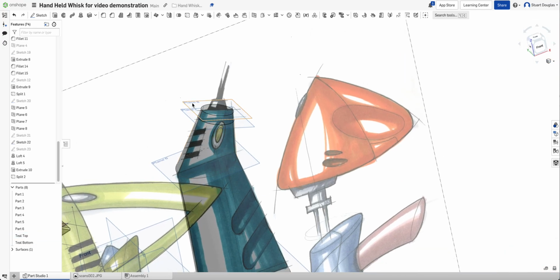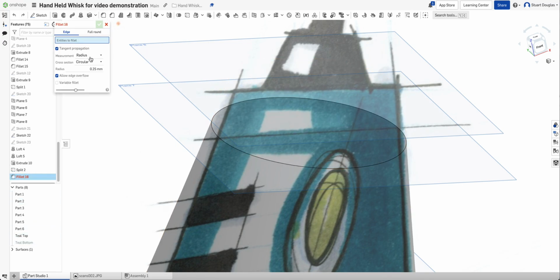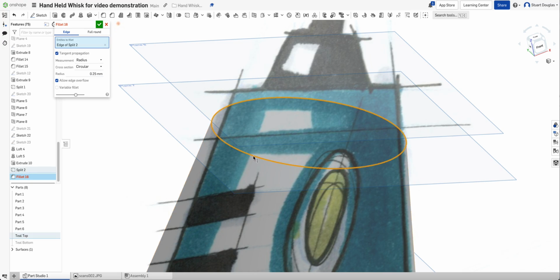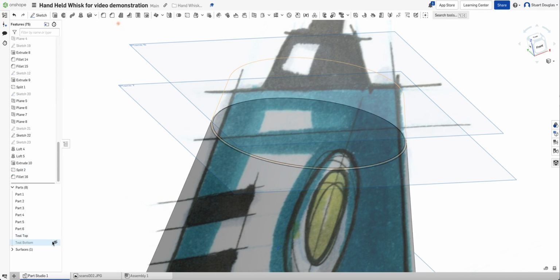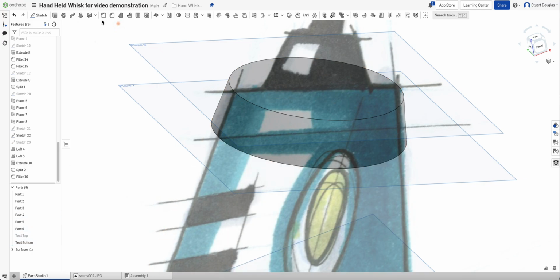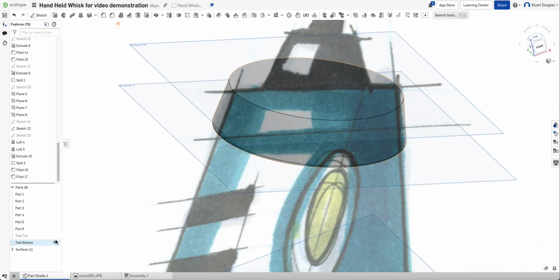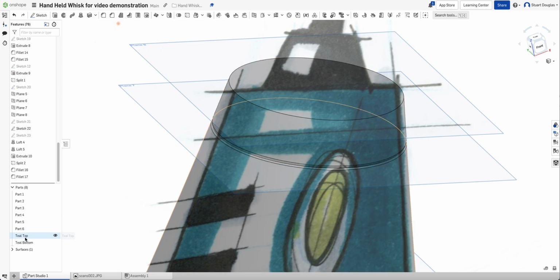The advantage of that is that by having 2 parts, I can apply a rounded edge, for example, a fillet. So let's take 0.25 to that edge there. Let's make it 0.5 and accept. Let's bring back and let's hide. And actually what you'll probably notice is I've named these two the wrong way round, which is a little silly. So this one should actually be the bottom.